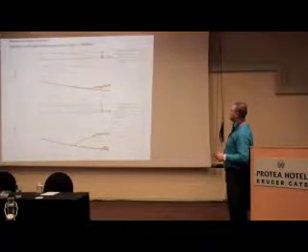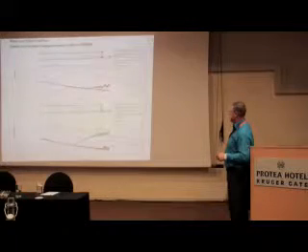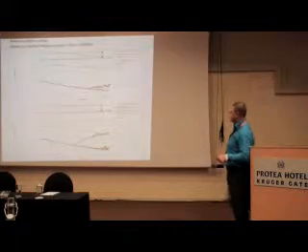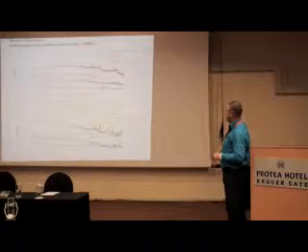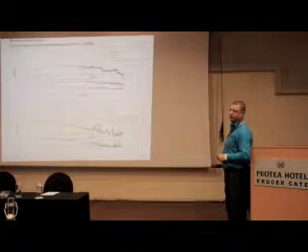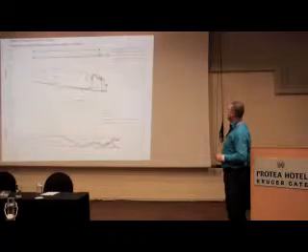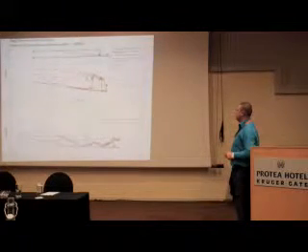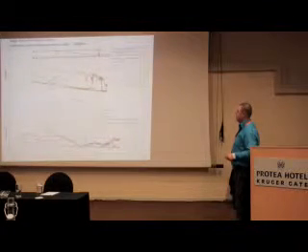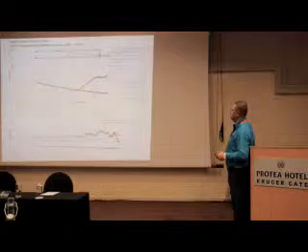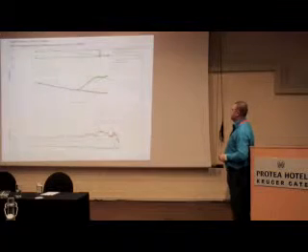This one is the mercury vapor lamp, which is a bit okay here, but here is not. This one is when using the electromagnetic ballast, it exceeds the limits, which is dangerous for the PLC channel. This is the high pressure sodium. It exceeds the maximum allowed signal level when using electronic or electromagnetic ballasts.